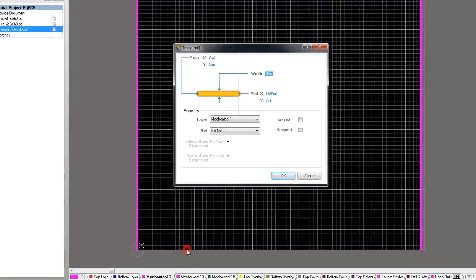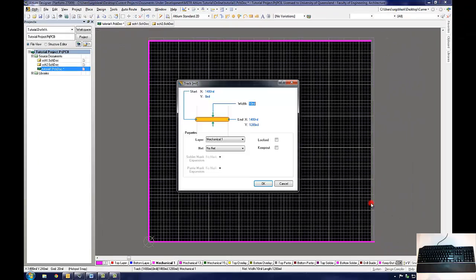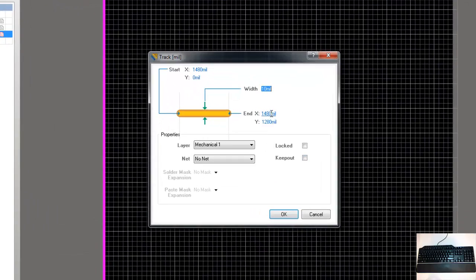By double-clicking a line from the board outline, the user can view and edit the line's properties. This is the most precise method of setting the dimensions of the line. The dimensions are defined using the document's XY coordinate system to set the start and end point of the line. Using this system, the user can accurately define the start and end point of each and every line of the board outline to give the PCB accurate shape.